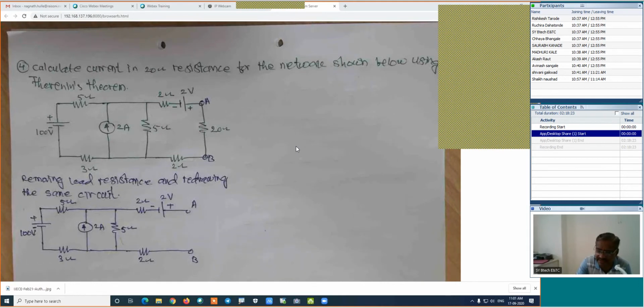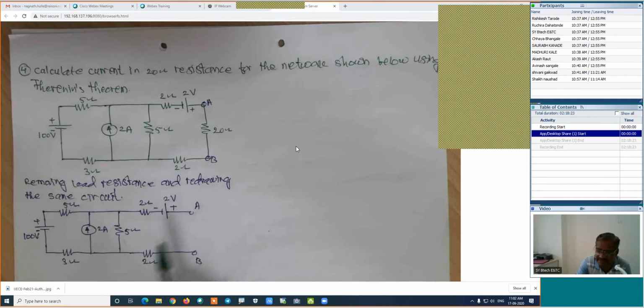I know that for you mesh analysis will be the simple one, but again here in this case, I will discuss multiple methods and then I will discuss the solution. Now look carefully. We can use nodal analysis also, because this point we can shift here. It's one branch, second branch, third branch. Current will not go in this branch, current will not go in this branch. That's why no need to think about those branches in the case of the nodal analysis method.